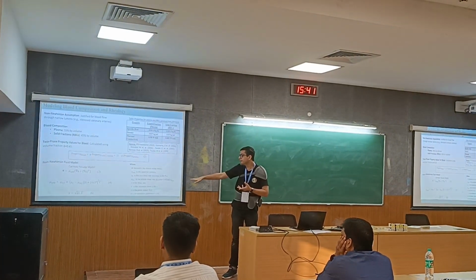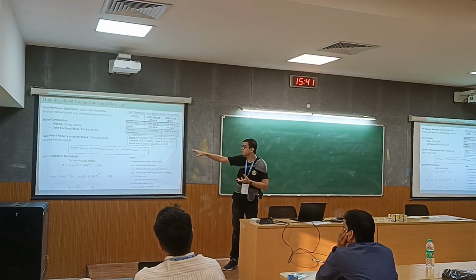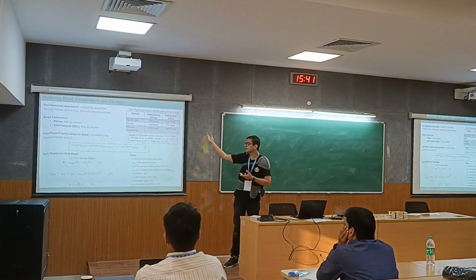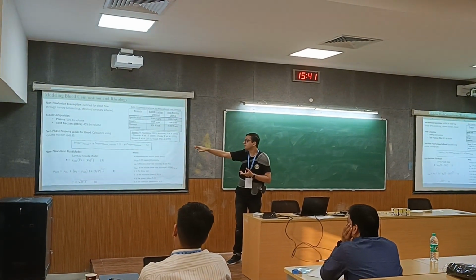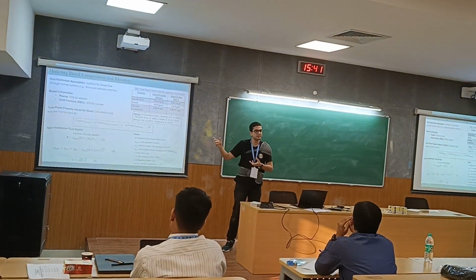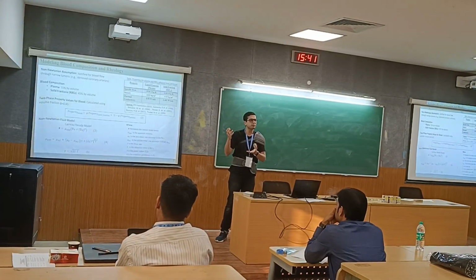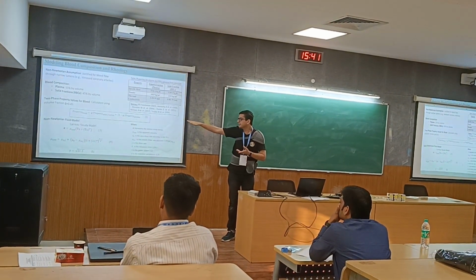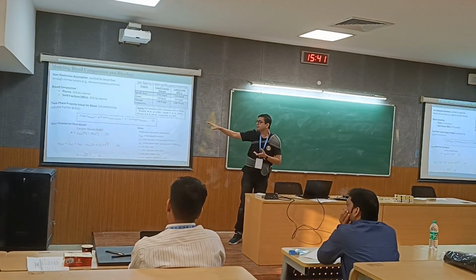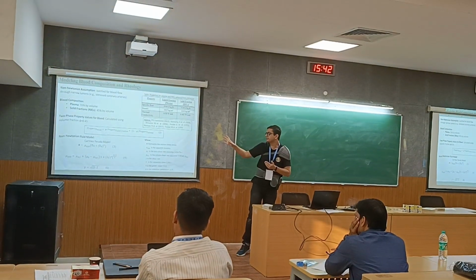The parameters that we obtained are also from literature, and we model the overall properties of blood, like the density, the thermal conductivity and specific heat, by this weighted average fraction, where phi is the hematocrit. The normal value for hematocrit is approximately 0.45, and the rest of the properties we took from plasma. This weighted fraction we used and inputted as the properties for the blood in the material section.